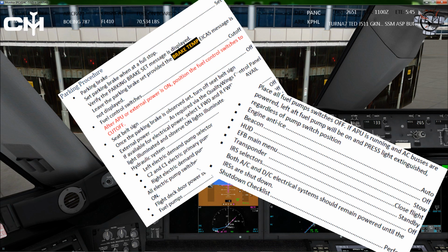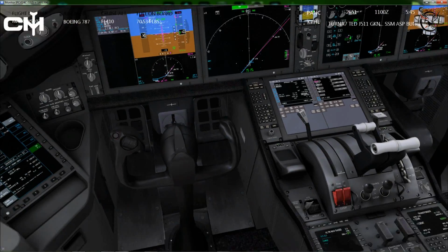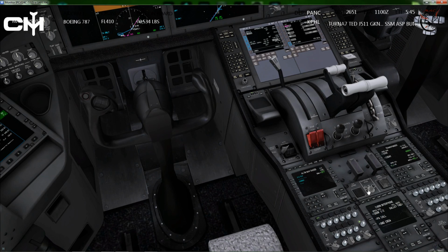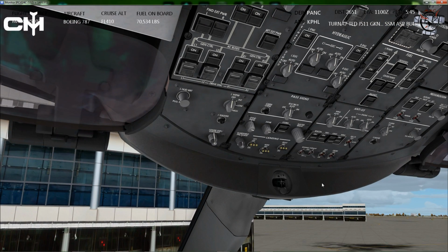It's ridiculous. Okay. As far as the after landing flow, speed brake, we brought it down. Flaps are up. Transponder was supposed to go to transponder mode, and it'll go to standby here in a second anyway, so I'm just going to roll it over. We should have turned the taxi light off as we pulled in here. I didn't do that. APU has already been started. Anti-ice as required. Lights off. That was landing lights and so on. And then weather radar off. I turned the weather radar off as we were approaching because we didn't need it anymore, so there's no reason to leave it on. Which is going to take us into our shutdown flow.